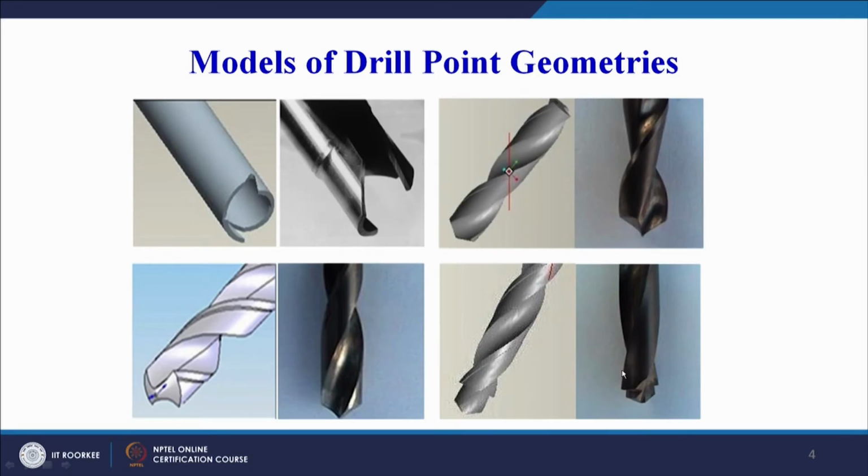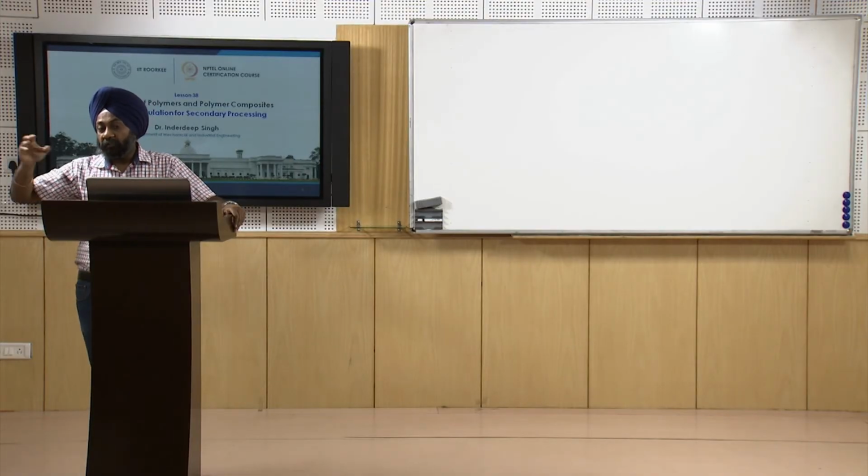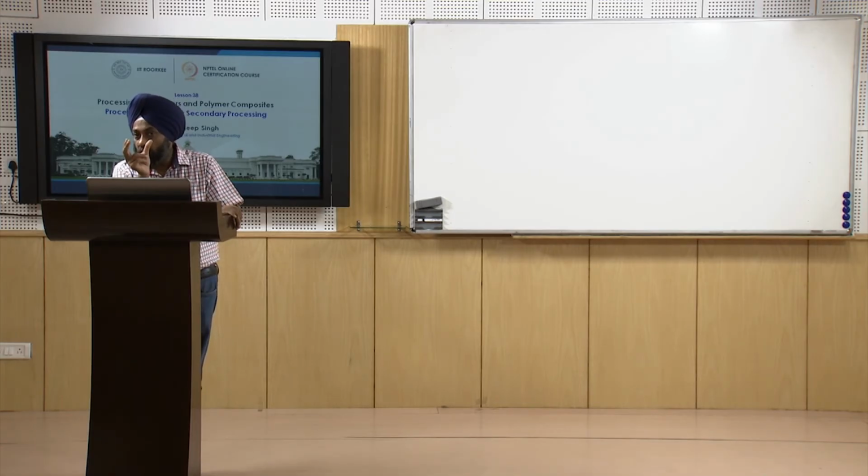And this is a step drill. You can focus on this area. You can see it performs the drilling operation in two stages, and if you remember, in one of the previous sessions where we saw the thrust force signal, that was for this step drill only, and I emphasized there very clearly that the inner portion of the drill generates a hole and the outer portion of the drill enlarges that hole to the specified diameter.